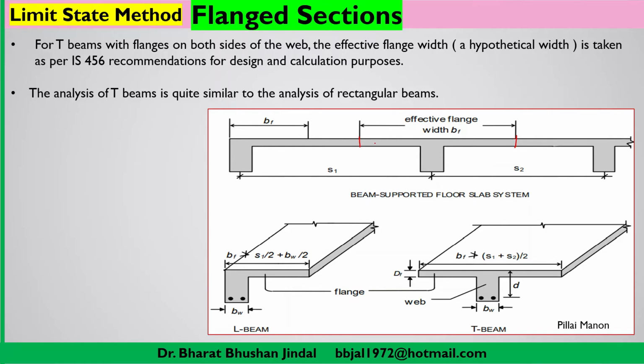So that means this beam as well as this portion of the slab you can design as a single component, as a composite section. Similarly, here at the end you can consider this portion of the beam as well as this slab. They will act as a composite section, and that will be termed as L section. So first of all, let us understand how to get the value of the effective flange of any T-beam section.